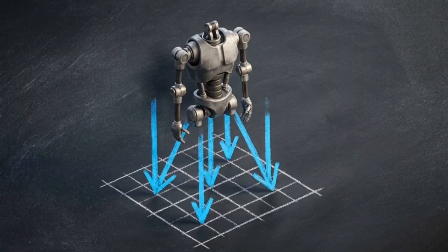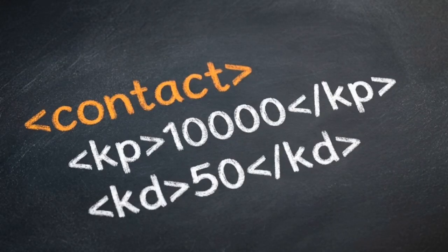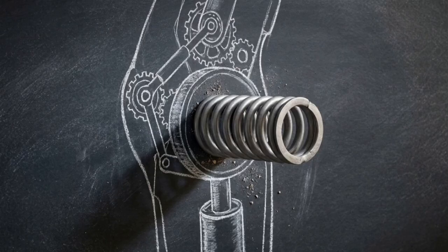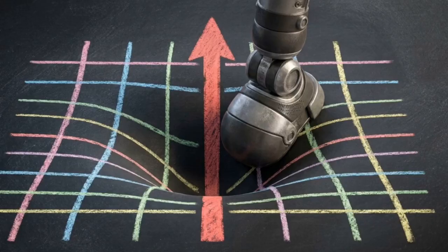Mapping the friction coefficient defines the horizontal boundaries, but the engine also requires an instruction on how the ground itself should respond vertically to the robot's mass. To configure that response, we move to the contact sub-block in the SDF file, isolating two specific values: stiffness, or Kp, and damping, or Kd. These aren't just arbitrary tuning knobs used to stop a robot model from jittering; they represent specific physical properties. Kp dictates the exact upward reactive force the ground generates when a robotic foot physically penetrates the floor plane.